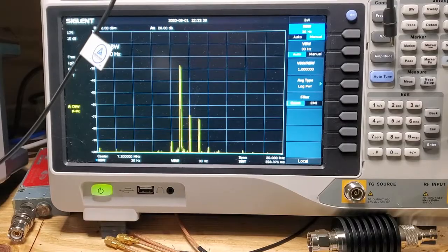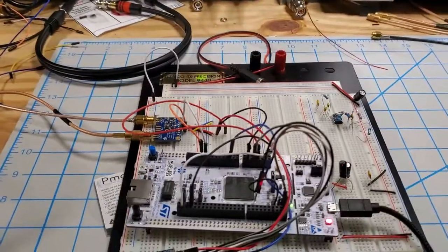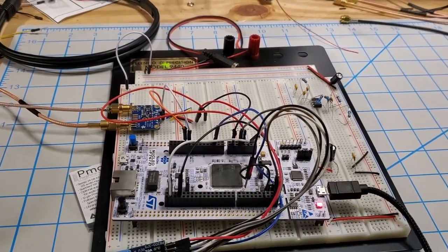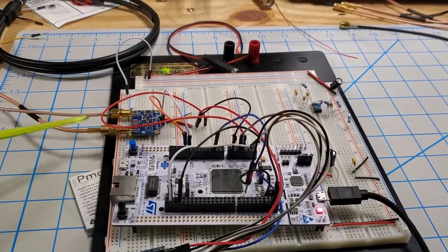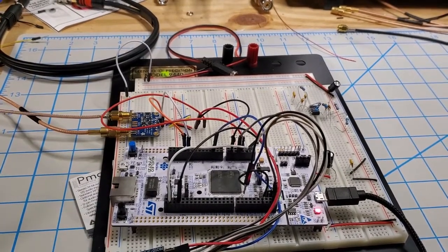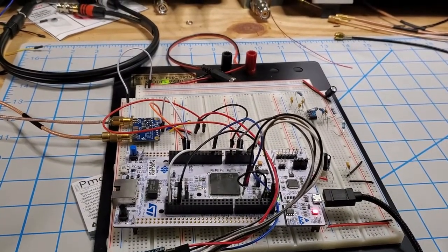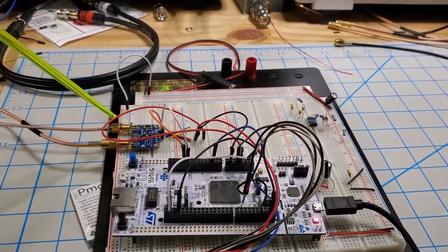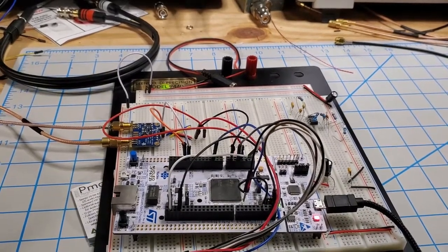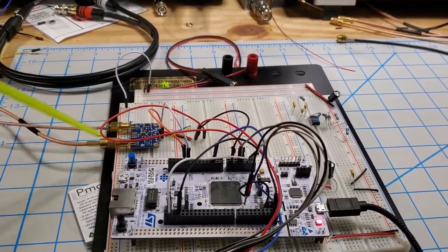Okay, so let's just go through the test setup we've got here, just panning down to the board. The board's all the same as usual. Just to note, I've included this software in here, I did include the SI5351 library here. Obviously I need that for the mixing, and basically what I've got coming out of here is 0 and 90 degrees RF signal at 7.2 megahertz. So that's coming out of here.